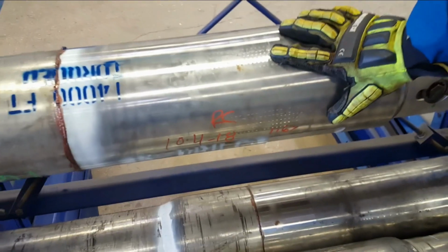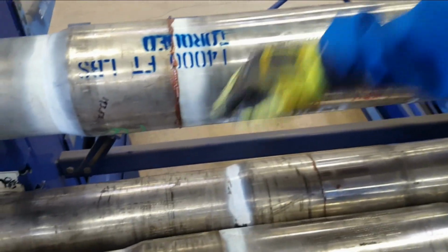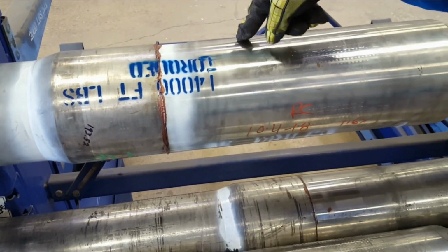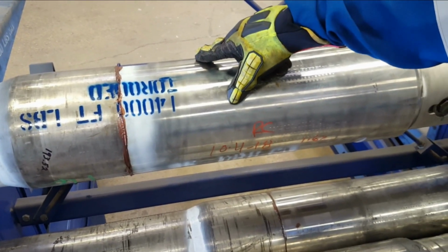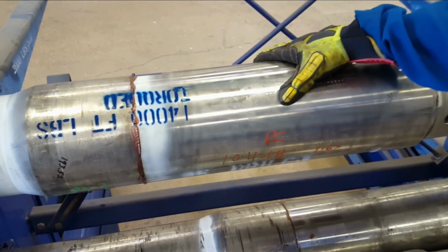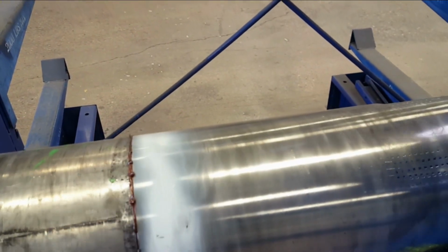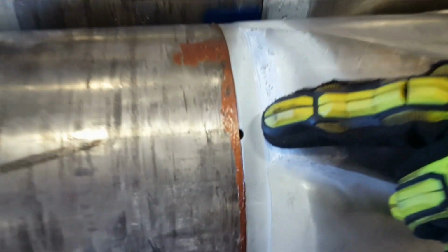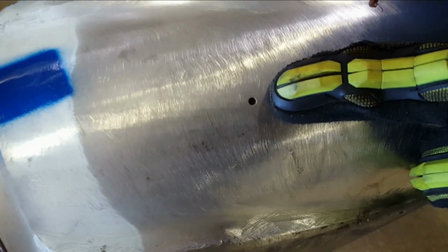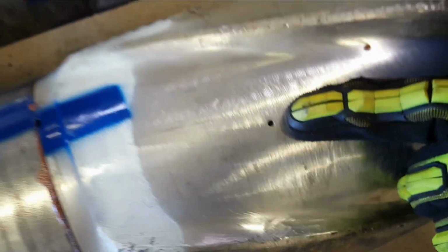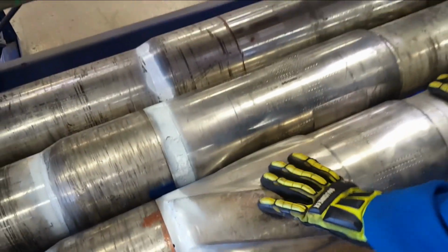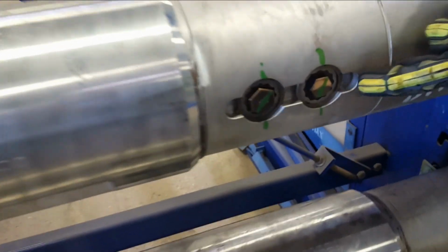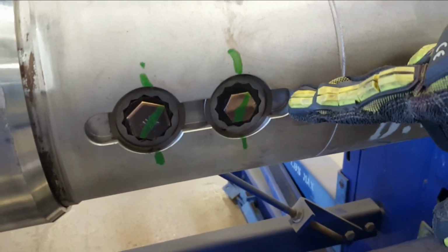If you notice a hole in a sleeve or a sleeve stabilizer, if it weeps mud from here or from a hole that's drilled somewhere around here, that's intended to be there. It's a small pressure equalization hole. So if you see a small hole, this one doesn't have one, of course. If you see that small groove, that's normal. And that small hole, that's normal. That's to equalize the pressure on that thread to make it easier and not store pressure. Upper anchor bolts. Those are the last two bolts on the 675 collar.